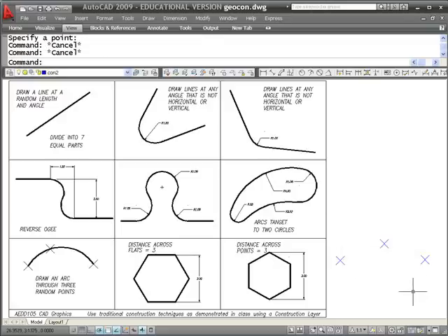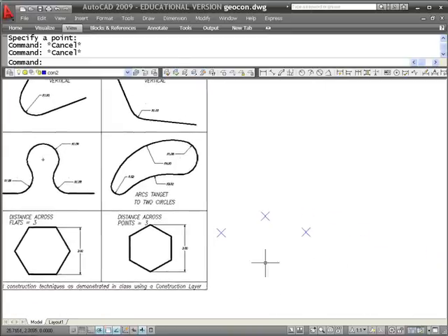What I want to do is draw a circle or an arc that starts here, goes through that one, and goes to there. Now, AutoCAD has several options that will allow you to do that. The arc command itself can be drawn through 3 points. But what we're going to do is use construction techniques once again, and here's what that would look like.